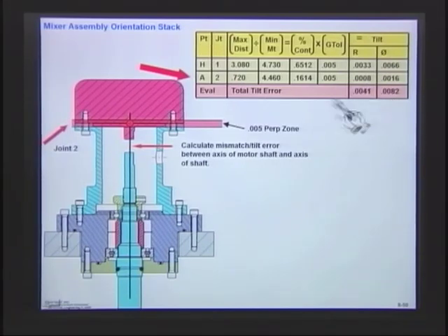It seems like joint number 2, the perpendicularity of 5, really didn't contribute much, right? We only got 1,000. But you notice this one here, we put down here. So this 5,000 contributed a lot more, right, to that misalignment. And you can see why, because it was a lot taller, right? You can see that right away. So you can keep that in mind when you're applying the tolerances later on, and see actually what that adds up to. And it's kind of common sense looking at them, kind of a rule of thumb. So that 5 thousandths there on a diameter gave us 6 thousandths.